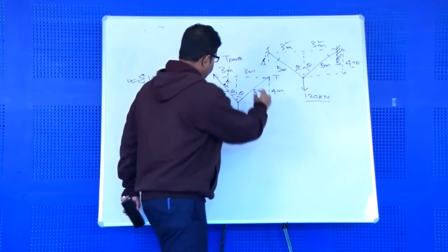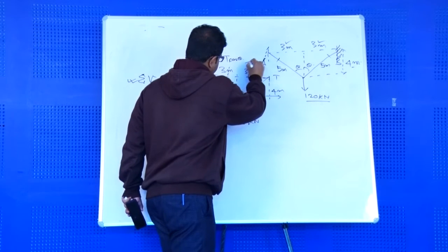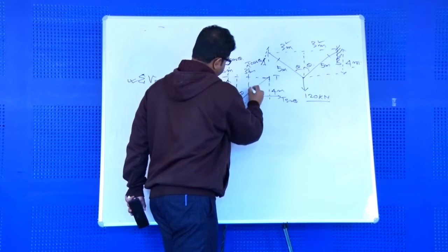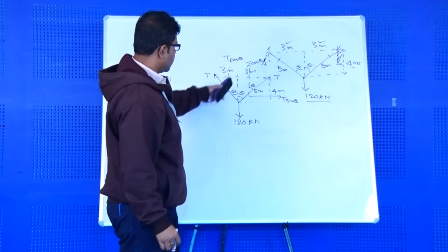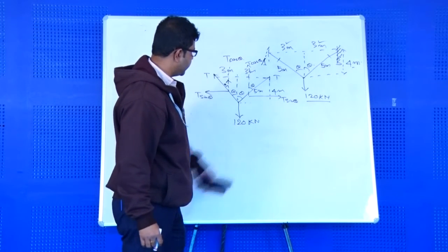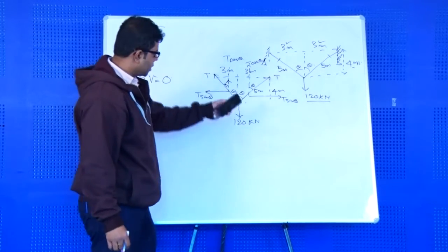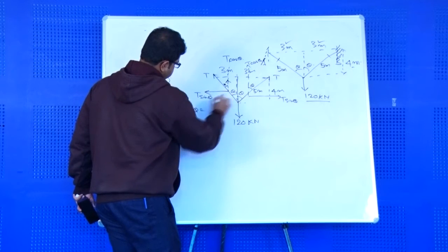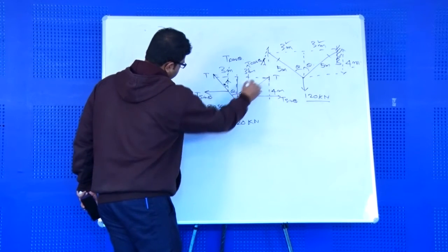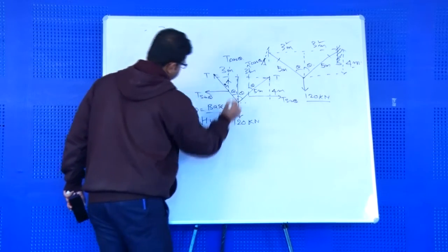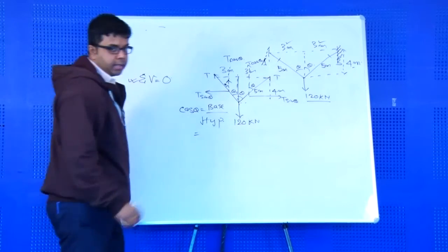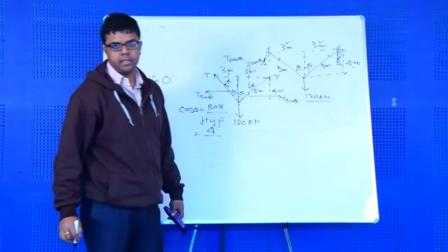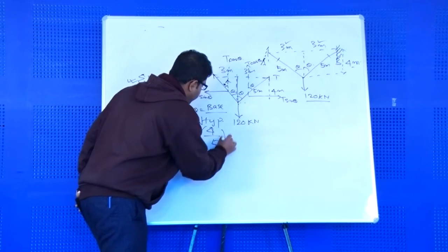Similarly, the tension in this segment: this is T cos theta and this is T sin theta. So theta will be represented here. Consider this right angle triangle. What is the value of cos theta? As per basic trigonometry, cos theta is base divided by hypotenuse. The base, that is the central dip of the cable, is 4 meter, and the hypotenuse, the one sided length of the cable, is 5 meter. Cos theta is 4 by 5.